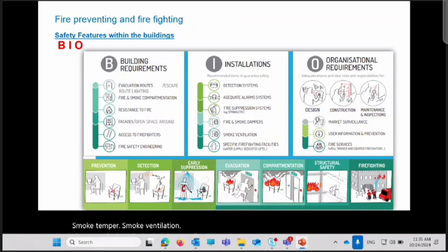Okay, and you must have some kind of arrangement in your facility. Do not accumulate unnecessary flammable, combustible, auxiliary material. Always do the housekeeping. Your stairs should be unobstructed. You must have proper tools and tackles like ladders and extinguishers. They should be inspected every month. For example, fire extinguishers must be arranged so you can timely recognize the risk associated. You have to inspect the extinguishers on a monthly basis.